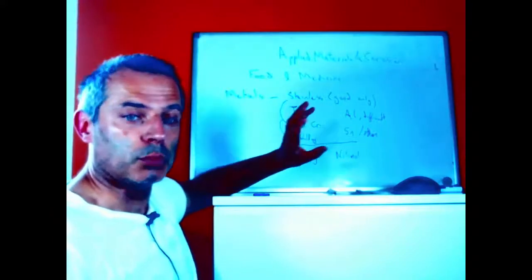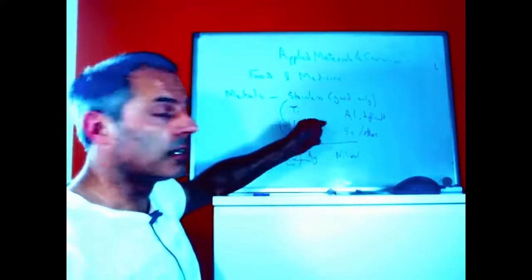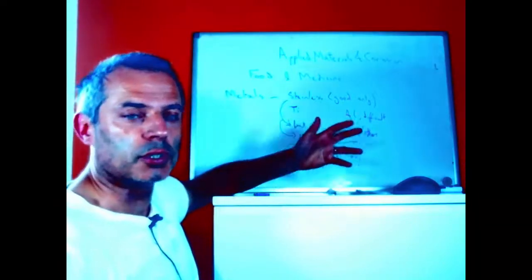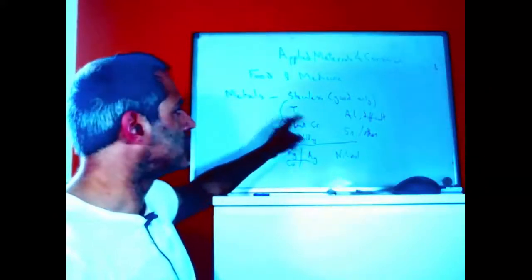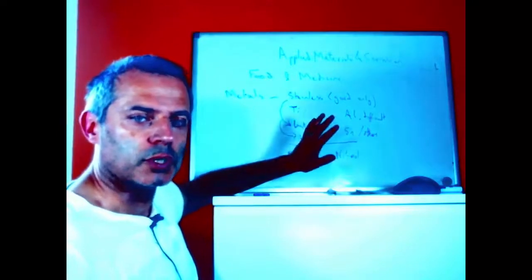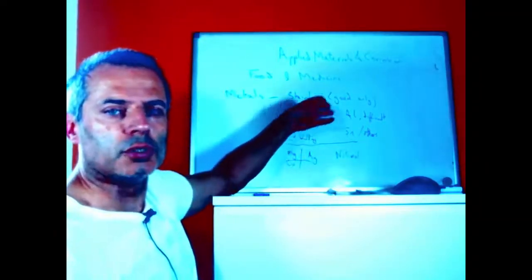Aluminium is quite difficult because we have to treat it to have a layer on the surface which is not going to release any material, which is not going to be susceptible particularly to steam. Steam is quite aggressive to aluminium, but once aluminium has a strong oxide layer on it, it's fine. It depends how long you want to use it, how many cycles.